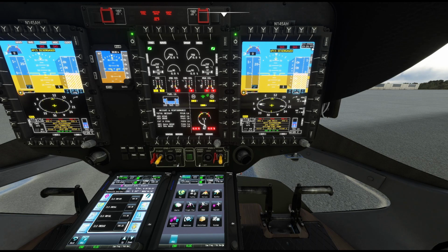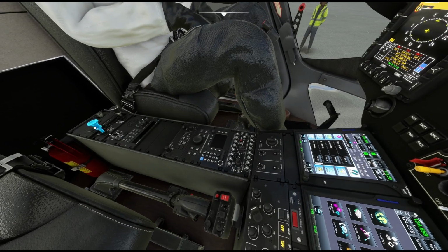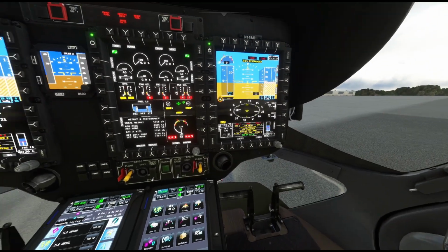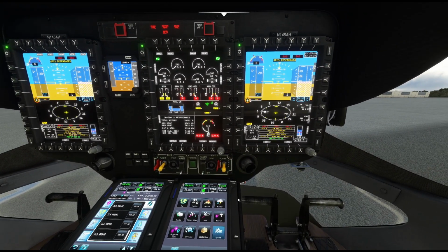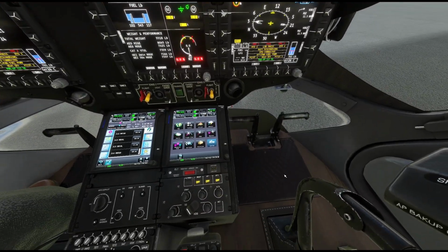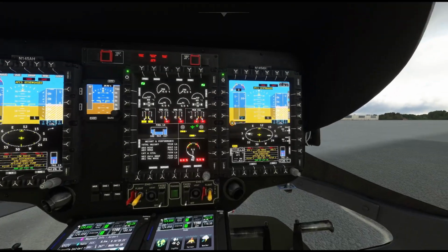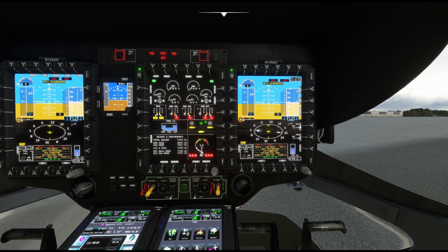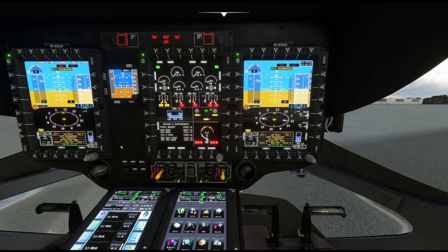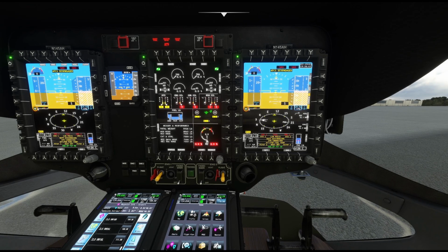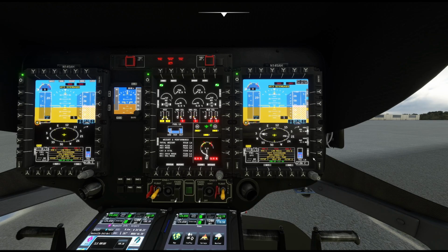Something to know is that this time is stored inside of the data transfer device, this thing right back here. And there's a keep live battery inside of there, so that when you power off the aircraft, it keeps the time. The first 34 seconds of the aircraft powering up, the AMCs, and specifically Aircraft Management Computer number 2, is pulling that time and comparing it with the time from this. And at about 34 seconds after power on, this should have gotten sufficient satellites and pulled a new fresh time, which loads it into the MFD2 and goes up there.